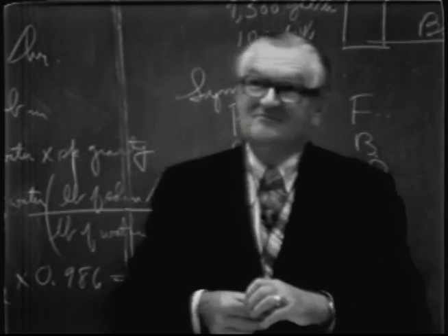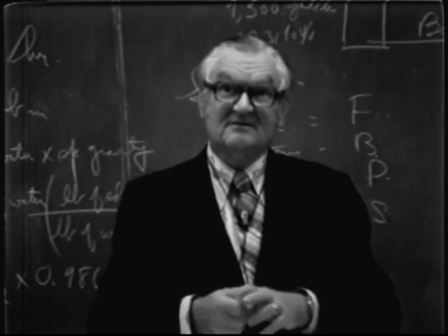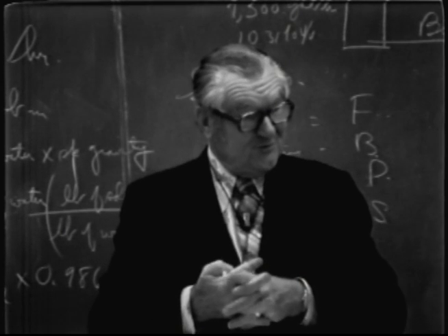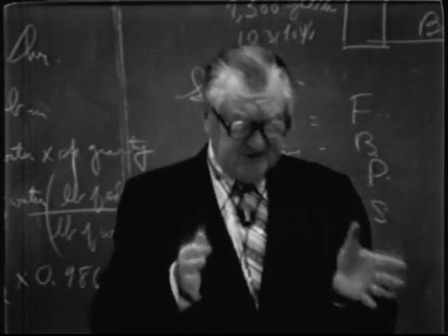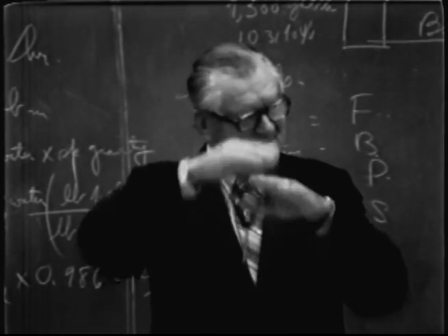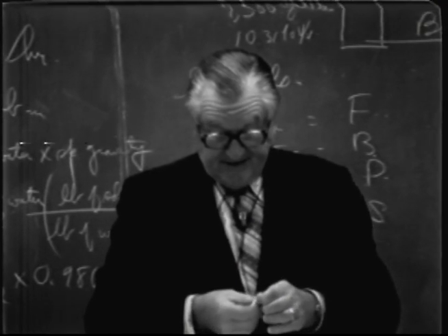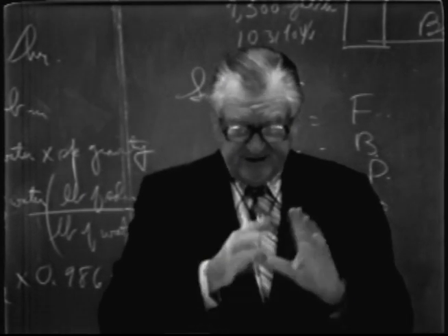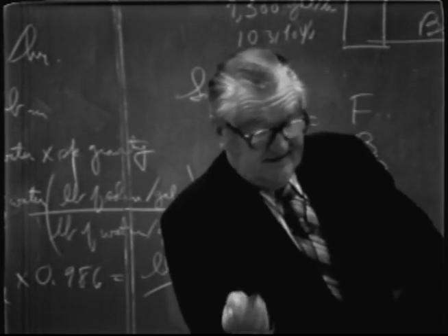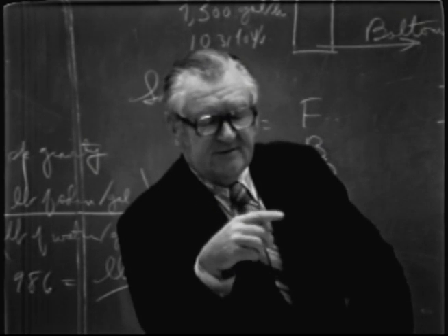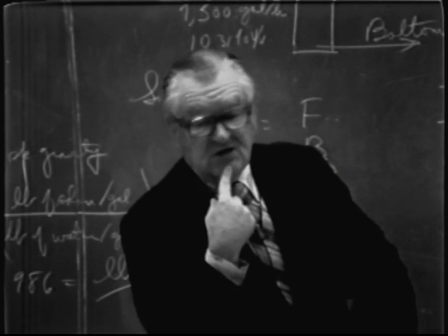Something like 450 BTUs per pound of alcohol and about 980 BTUs per pound of water. And so the heat of vaporization, which we're concerned with when we're talking about distillation and multi-stage vaporization, on a weight basis would be a function of the concentration, but when we convert to a mole basis, the heat of vaporization is almost constant.